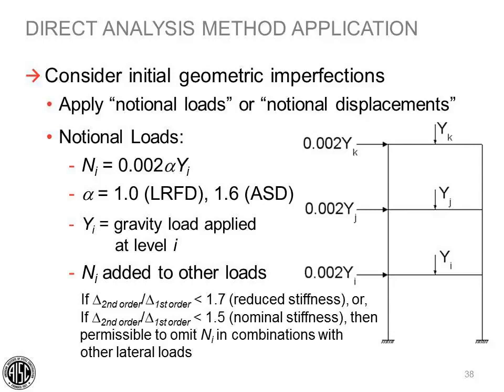You do have the option of modeling the out-of-plumb geometry instead of applying notional lateral loads. However, it's often easier to apply the notional loads in each direction than it is to provide different starting geometry for each direction, so usually people apply the notional loads.